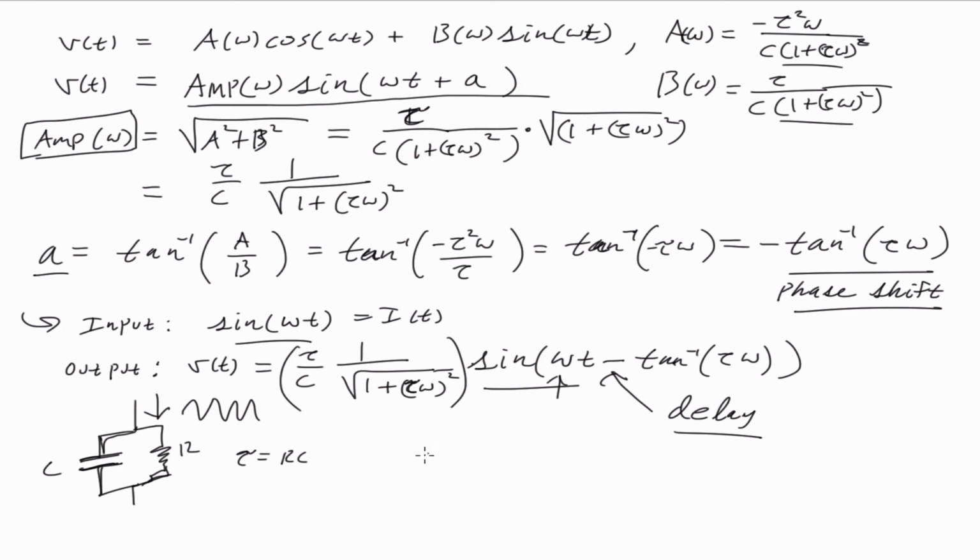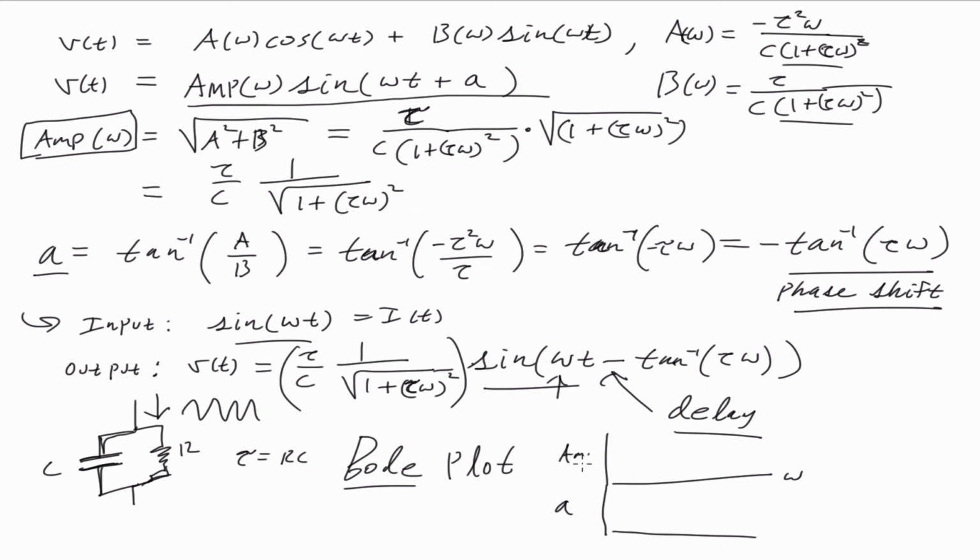And so actually I went out and plotted this. This is called a Bode plot. That's a guy's name. What you do on a Bode plot is have an omega, and it's actually two plots put together. One is your phase, and the other one is the amplitude.